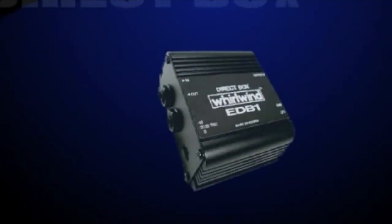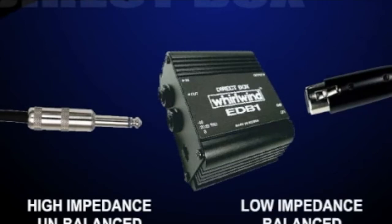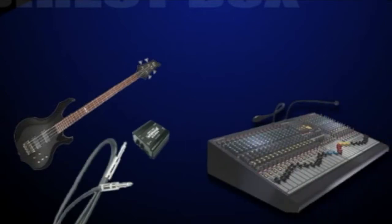The most common impedance matching adapter is known as a direct box. A direct box converts high impedance unbalanced to low impedance balanced. The most common use of a direct box is to connect keyboards, synthesizers, bass guitars, and other line-level devices into the audio system via an XLR microphone input jack.